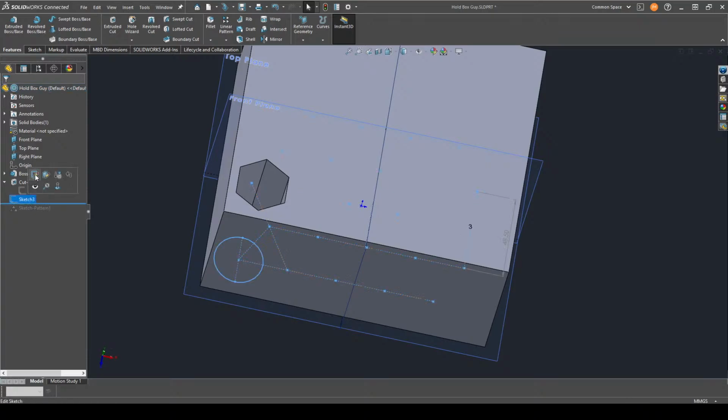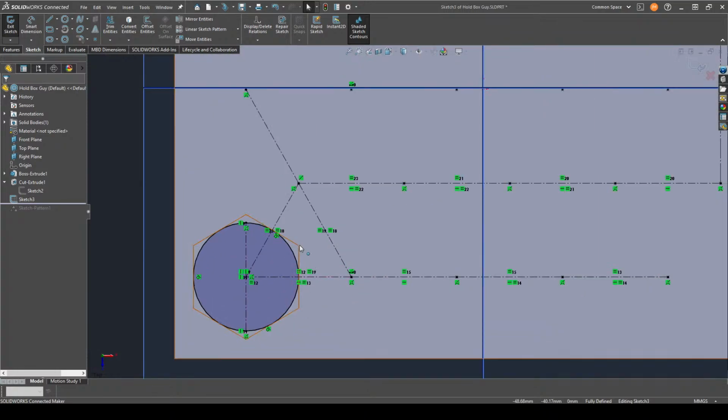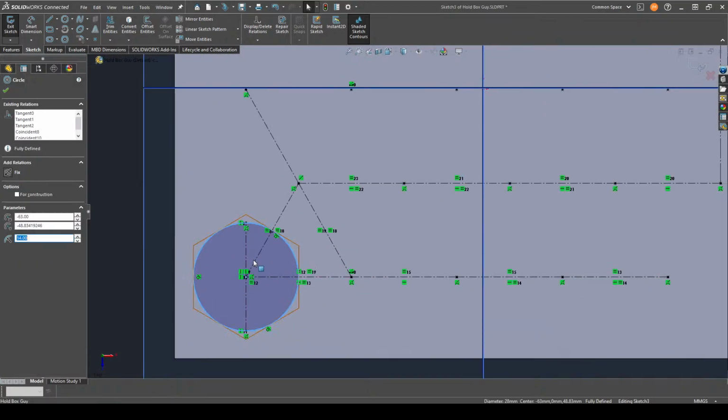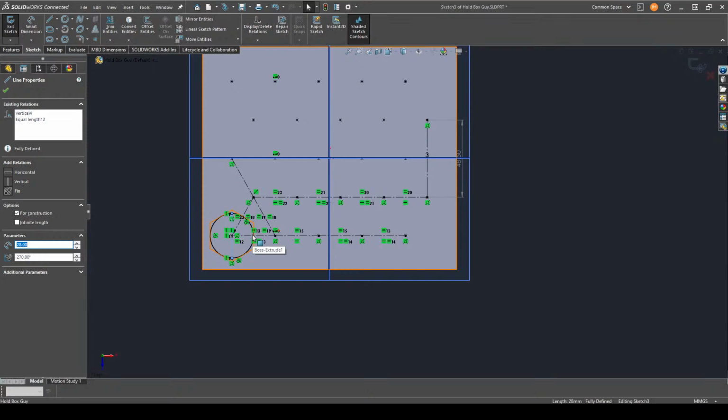This next bit here, this is my defining sketch. So this sketch is for this pattern down here. I want to have about 5 rows of paint, and since they're hexes, they need to be staggered to have ultimate packing efficiency. So I just got them staggered, and I did a few fancy things here. The first thing I did was I used this circle to help figure out where the center of this hex is. So if I were to move this guy later, it still follows along with it, as well as having this line here to define the diameter of that circle.